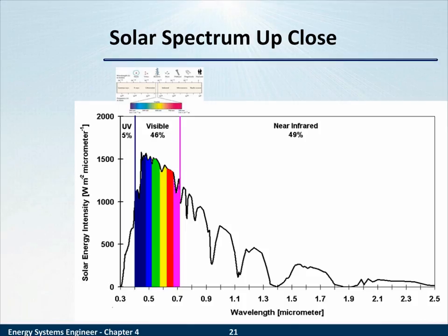So indeed, you can calculate total solar energy rejection using the proportional rejection of UV, visible, infrared, and their proportional energy. You see here why I said earlier, 100% UV absorption does not cause glass breakage, whereas maybe 55% total solar energy absorption can cause glass breakage.